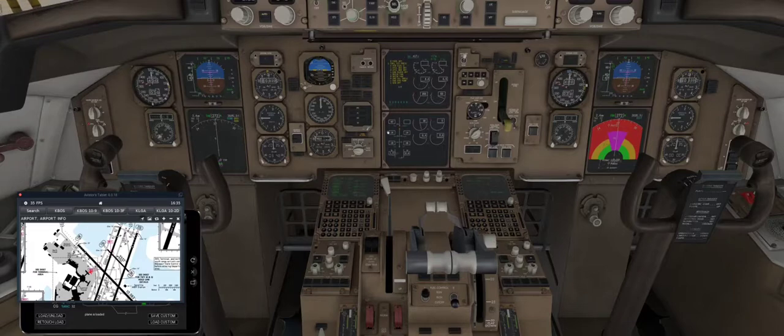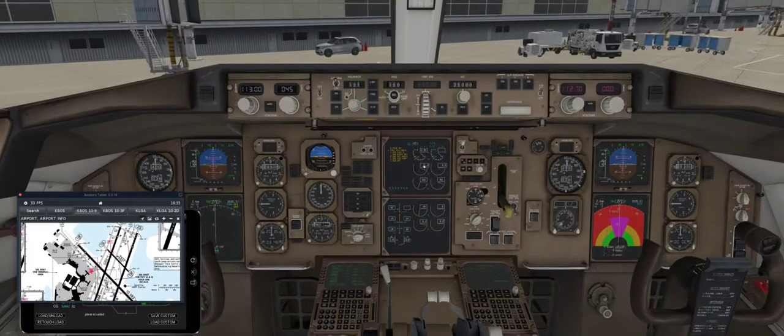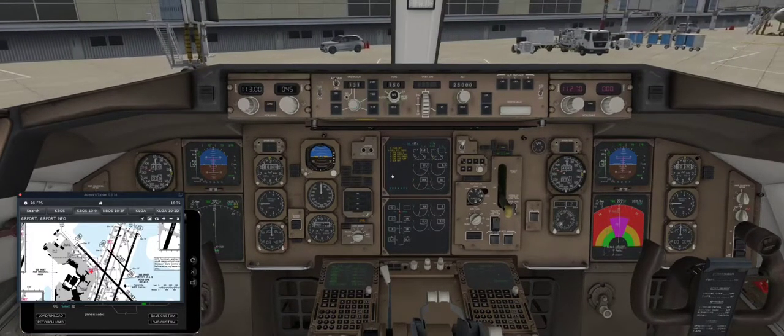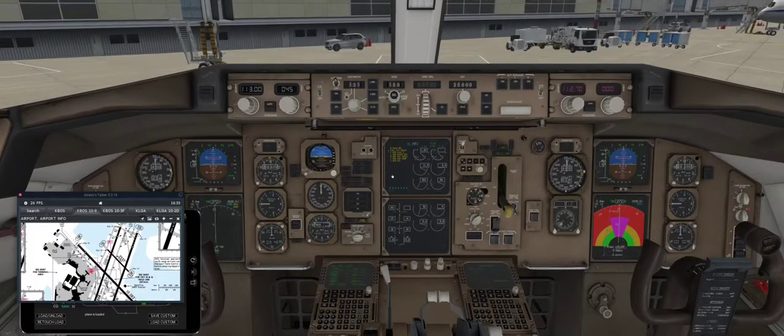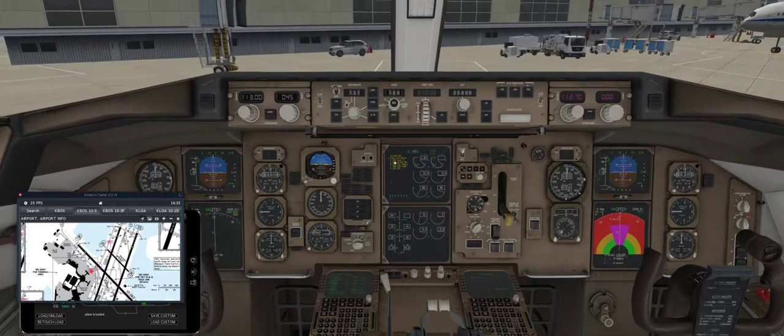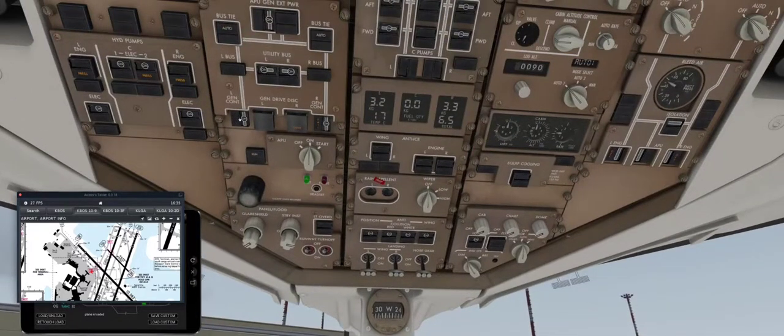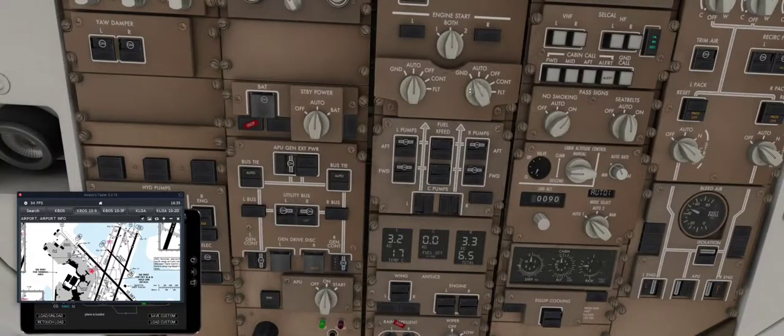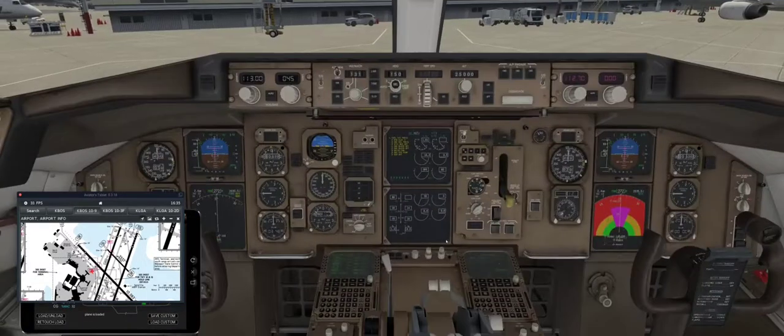Oil pressure. We see things happening. Exhaust gas temperature. If I had improperly started the engine, you'd see it way up here. That's not good. Good. RPM's coming up. And pretty soon you'll see the fail light go off there, and we can engage hydraulics on that side. And now we can do co-pilot engine number 2.